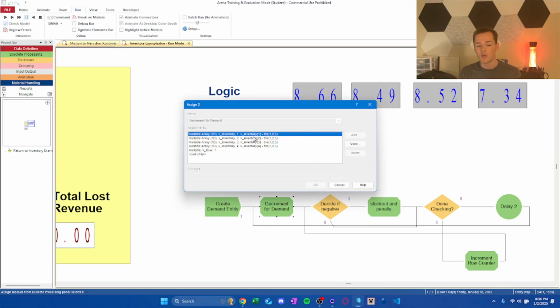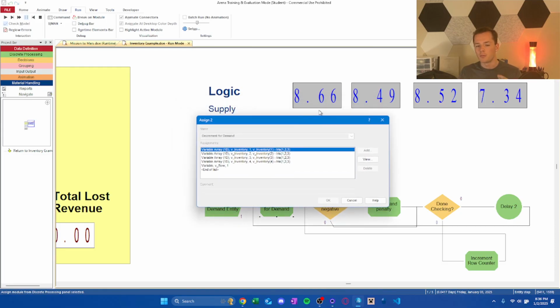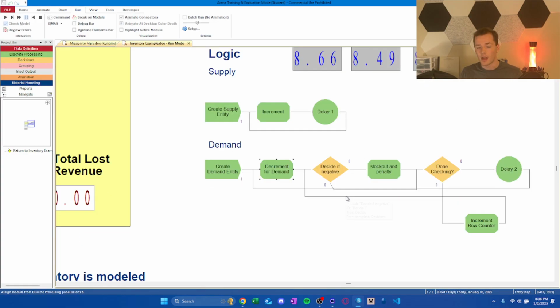Demand again will be equal to, it's a triangular distribution, so we should see that values between 1 and 3 are subtracted off of these current variable counts right here, or the inventory counts, which they are. So as you can see, it took just a little bit, 1.5 from 2 of these, and then 2.7 from this fourth one. So if that happens again, 2.7 will be the first one that runs out. But at this point, we actually do need to run through the entire process here.